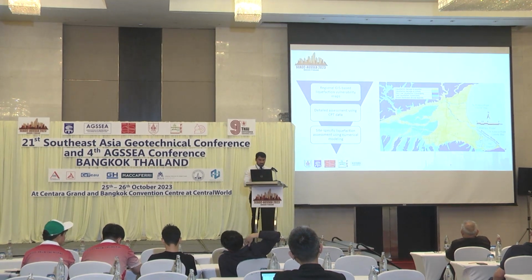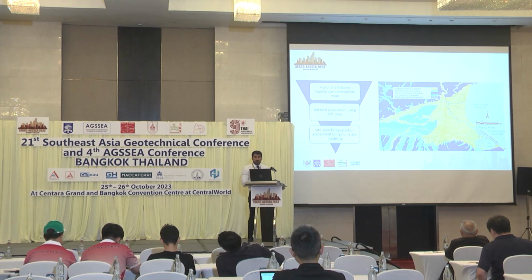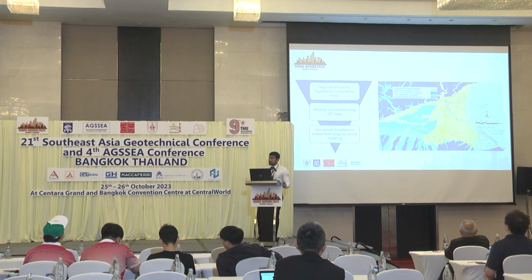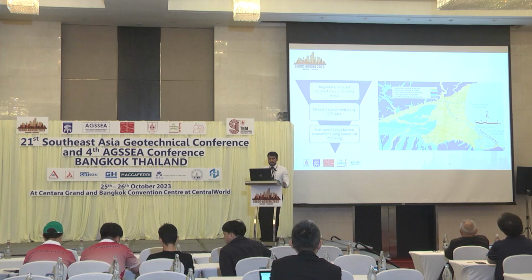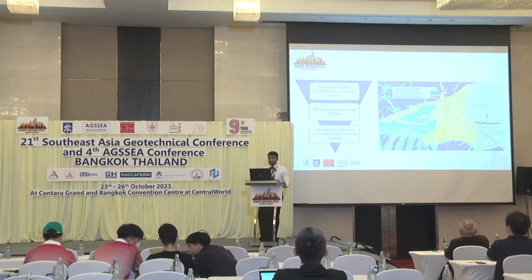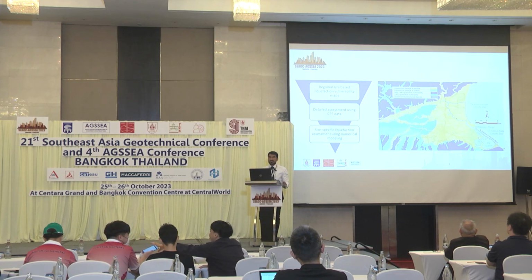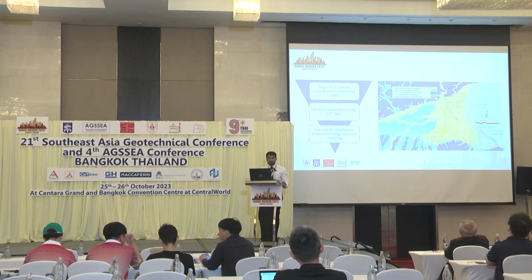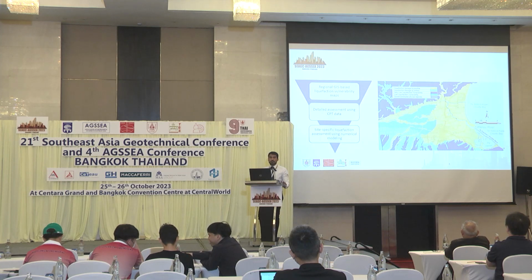So this figure shows some of the background. Before doing the numerical analysis, the first step I took was to map the whole region, a GIS-based map. A methodology was adopted for that, in which the idea was to map using the groundwater depth, age of the deposits, and the sediment types to see which areas are prone to liquefaction, and whether liquefaction vulnerability is high, low, or medium.